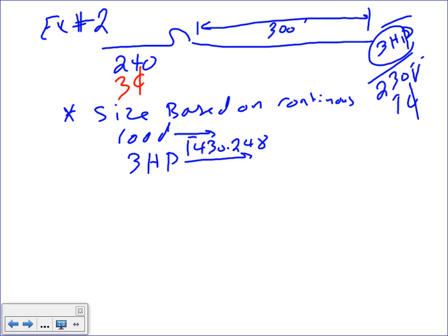We do, but we don't know why we're using that. Ah, because we're sizing. Good. A couple of minutes ago, you told us we used the full load nameplate of the motor. Do you see any nameplate there? Did I give you a nameplate? No. So what are you going to do? You don't have the nameplate. That's what you're going to face as a designer. What you know about the motor is the horsepower, and you have no idea what the nameplate is yet. So what do we do?